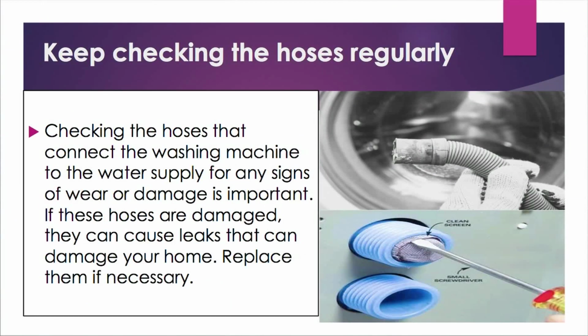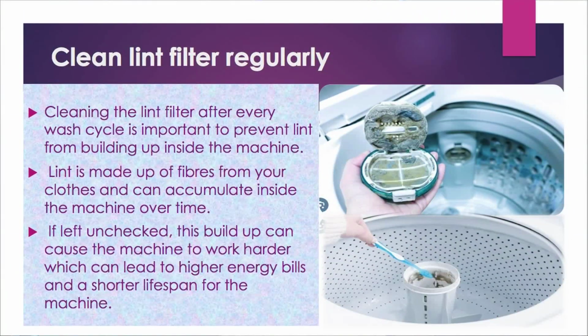Third point to be remembered, you have to keep checking the hoses regularly. Check for any sign of wear or damage. It's important, because if these hoses are damaged, they can cause leaks and that can damage your home. Replace them if necessary.